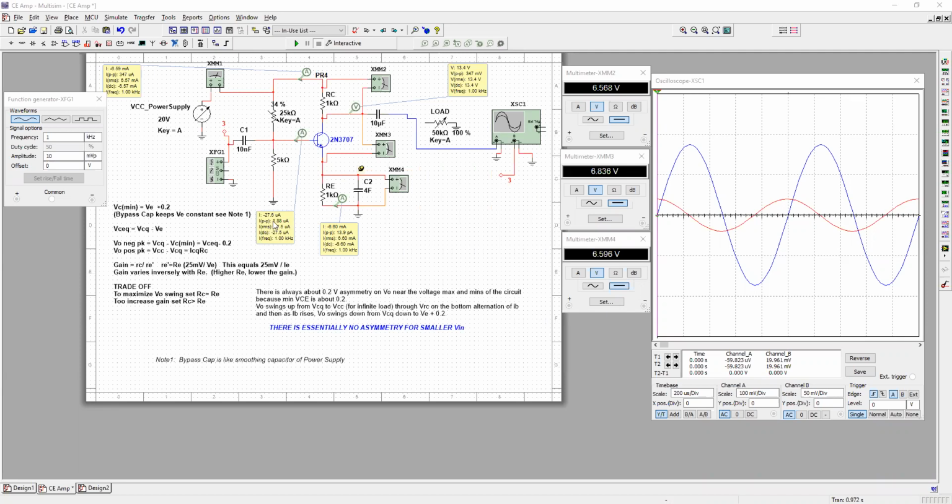So that voltage is part of this loop here. We see that the 5 kilo ohm voltage is going to be fixed by the VCC and the voltage divider. So that's not changing. But the voltage across RE will rise if the current through the collector rises. That's going to squeeze the voltage across the base and emitter. KVL demands it. That's going to reduce the base current, the current that's feeding the transistor. That's going to reduce the collector current then. This is a stabilizing factor.